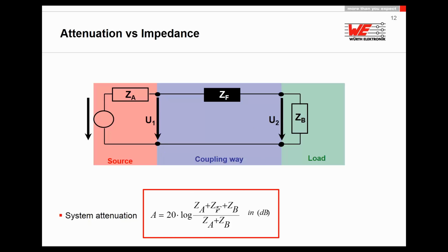You just have to take ZF out of the logarithm, put it on the front, and make an equation in exponential. But even that is not helping too much, because to use this formula you need 2 additional pieces of information: ZA and ZB, source impedance and load impedance. Well, in a university it's simple, everything is 50 ohm.